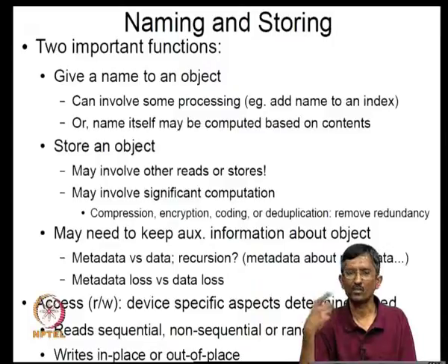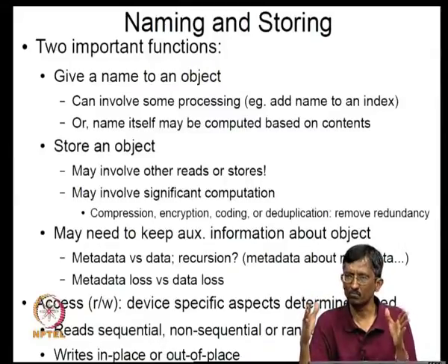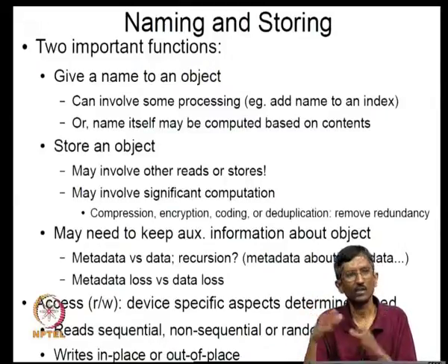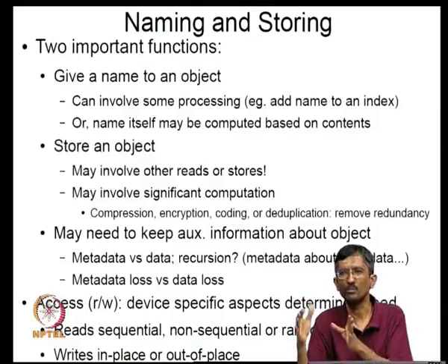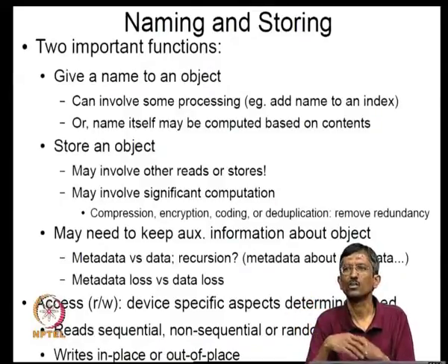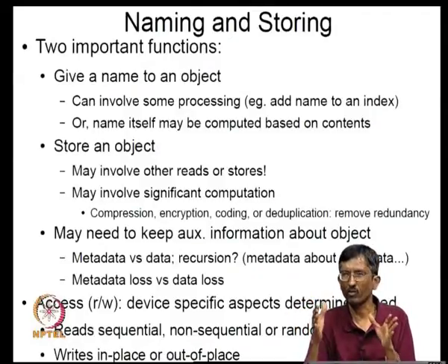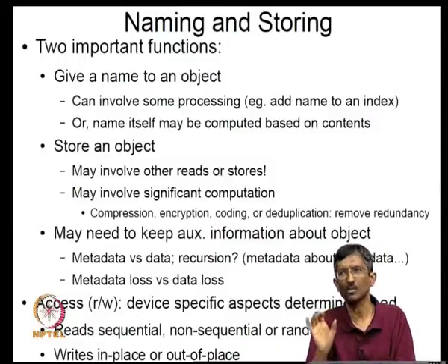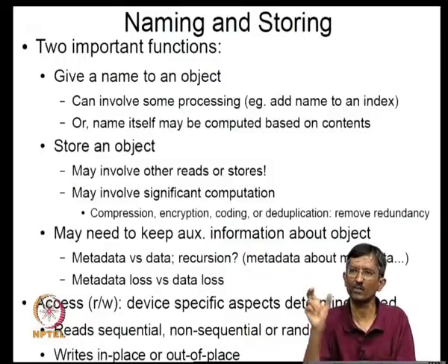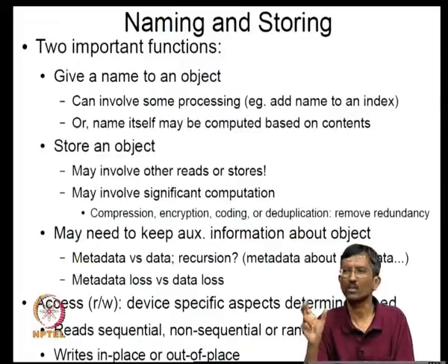For example, in disks they use something called Reed-Solomon coding widely, and for example, for every 512 bits, as much as about 40 to 50 or 60 bits are used to encode that 512 bit, so that even if a burst of errors takes place, for example 4 or 5 bits get lost or even 10 bits get lost, I can still recover the whole thing.